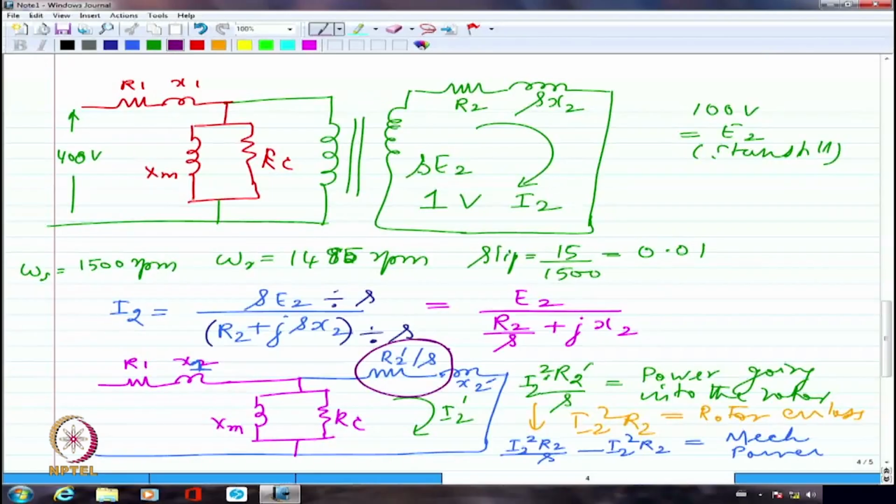So I have given 100 divided by 0.02 as the total power to the rotor, out of which 100 watts has been dissipated. So I am going to have the rest, 100 by 0.02 minus 100, as the total power that goes towards mechanical power conversion. Got it?